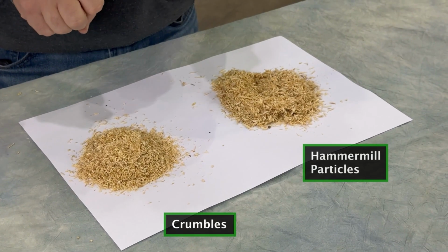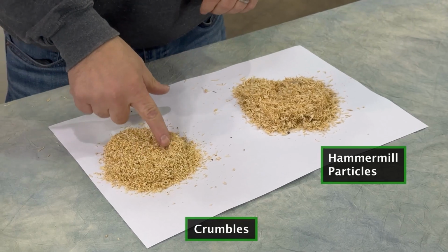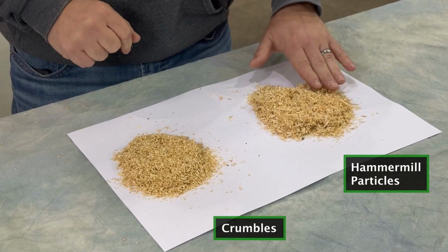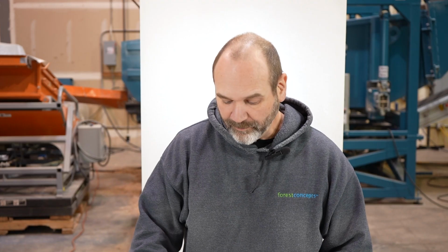The size reduction process or mechanism makes a difference in how the material geometry comes out. Both of these materials have the same nominal particle size, so the center of the peaks are about the same spot. This has a tighter or a narrower particle size distribution, while this one has a wider or a broader particle size distribution.